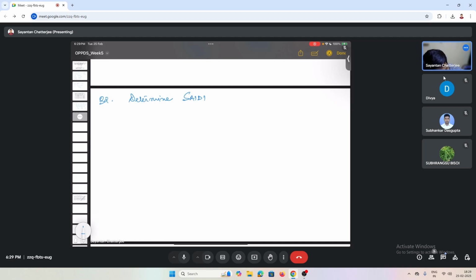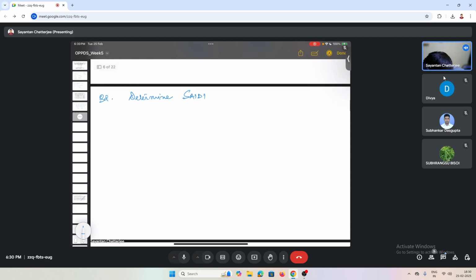Again, what is SAIDI? The previous one was SAIFI, so it was only the number of customers. But there may be cases where a single customer can have multiple interruptions. So the duration of the customers with the interruption time is to be taken into consideration.